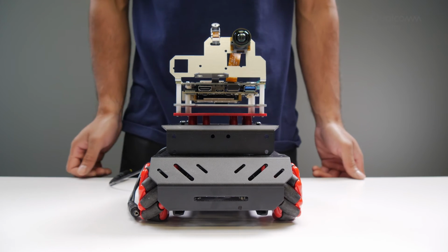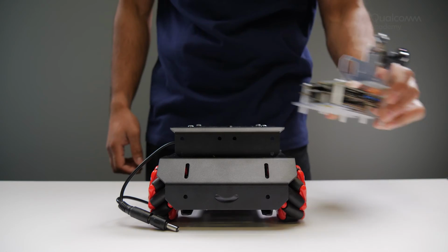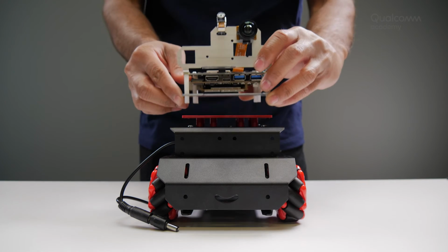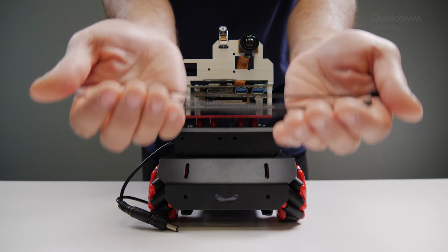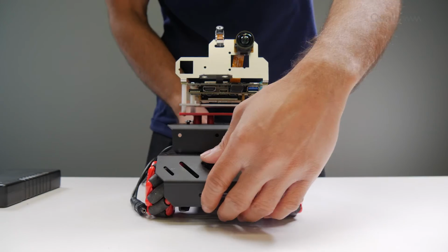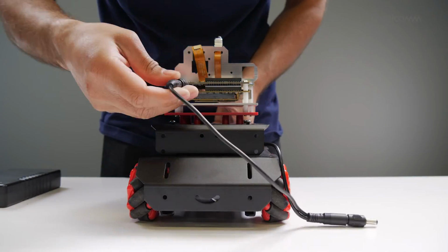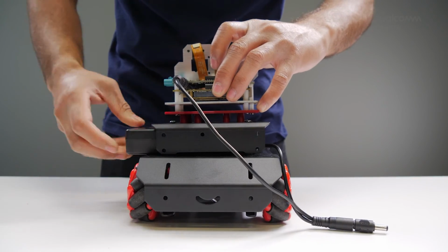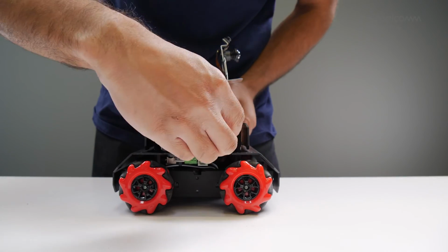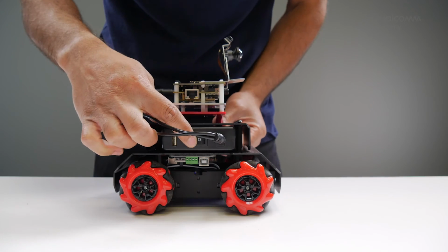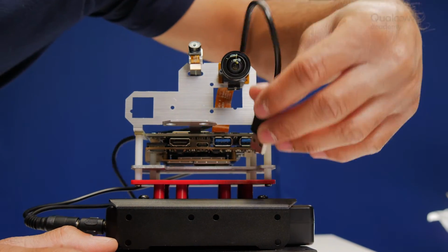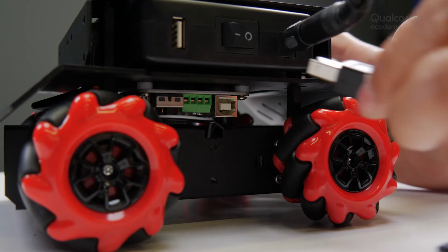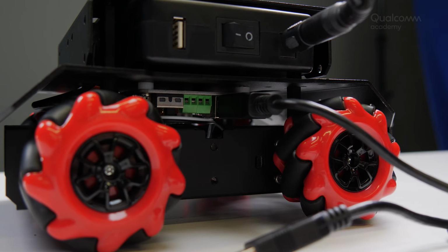Now we'll attach the RB5 board to the MBot. In my case, I've 3D printed a small bracket to put the two together, but just zip ties are sufficient as well. Once you've done that, you can connect a battery using the DC barrel jacks on the RB5 and the MBot. Finally, you'll need to connect the RB5 to the MegaPi board under the MBot via USB.